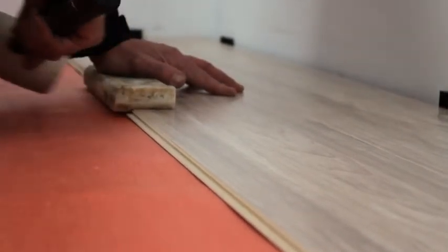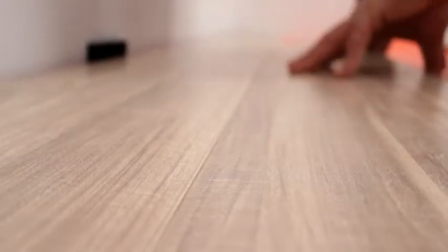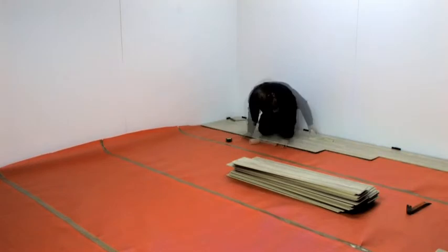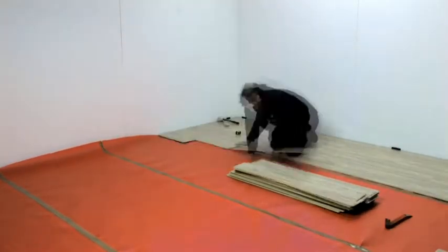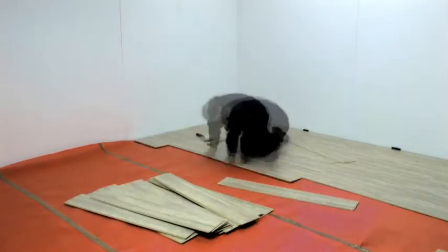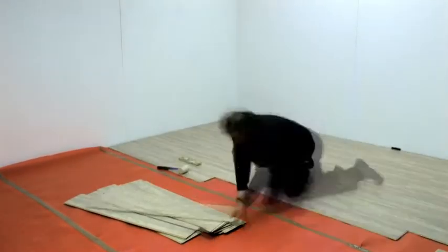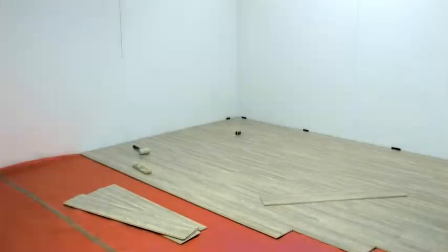To make the whole operation easier, lay the floor so that on the long side the female joint leans on the male joint, while on the short side, use the opposite approach and fit the male joint under the female joint. Continue this way for the whole surface of the room, always allowing for 1 centimeter of distance from the wall to ensure that later on the elements have enough room for their natural expansion.